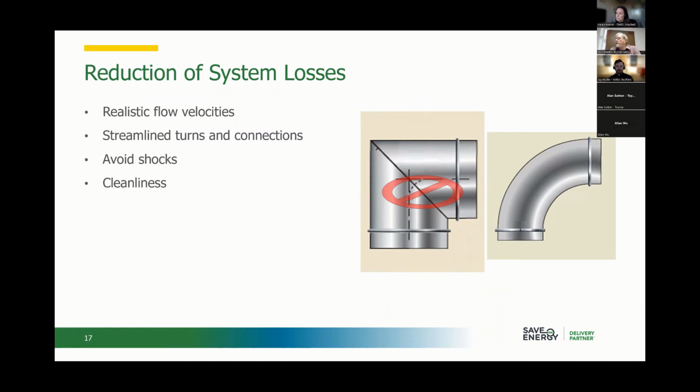What else have I got here? Oh, I got one here I'm going to show you. And this gets back to what happens at the inlet of a duct. So let's assume you've got a round duct this time, and you've got a duct that's just sticking out in the middle of some place, and you're trying to bring air in. You know what? You're better off putting some kind of a bell mouth on that to help get the smooth, so the air can get around the corner and into the fan.